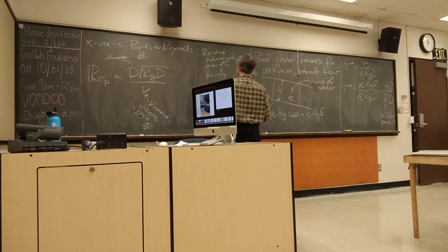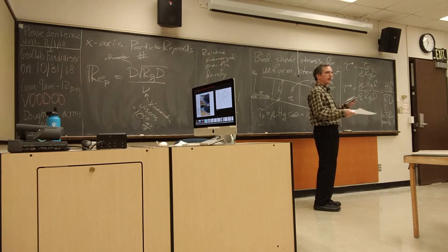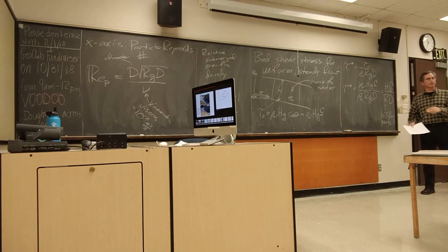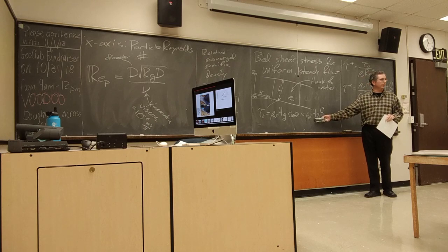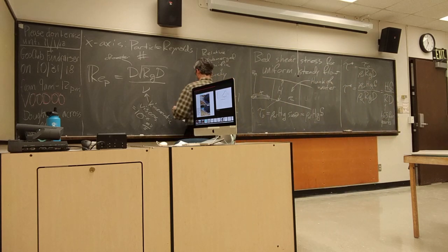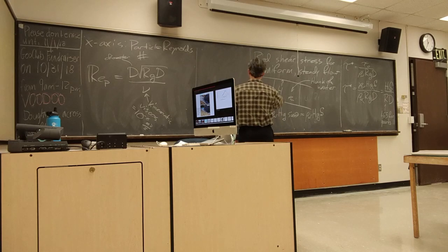So, how good? Okay, if we're going to use this Shields diagram, I said it's kind of fuzzy, so maybe we can get away with some slop here and there. I've already thrown in some approximations. It's worth asking, okay, well, just how good is this uniform steady flow hunk of water type approximation? Because it seems a little odd that we can just treat water like it's a big hunk of earth. So that's a decent question if you had it, and it's probably worth addressing.